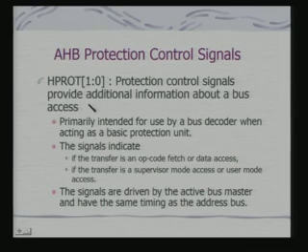These are called protection control signals, which provide additional information about a bus access. It is primarily intended for use by a bus decoder when acting as a basic protection unit. Okay. So, the signals indicate if the transfer is an opcode fetch or data access, and if the transfer is a supervisor mode access or user mode access. Okay. The signals are driven by the active bus master and have the same timing as that of the address bus. Okay. So, these are protection information and we call these protection data.